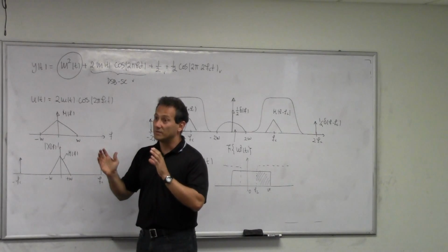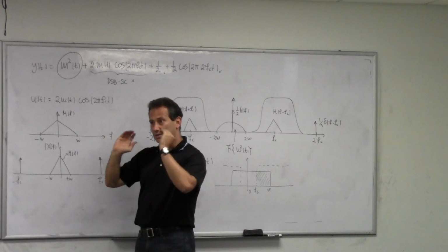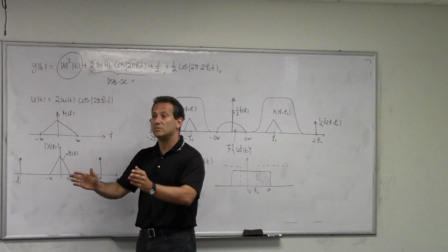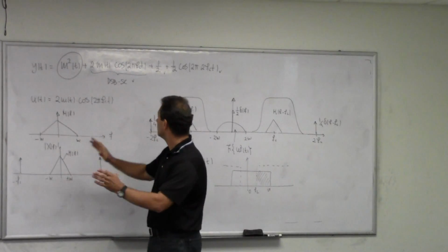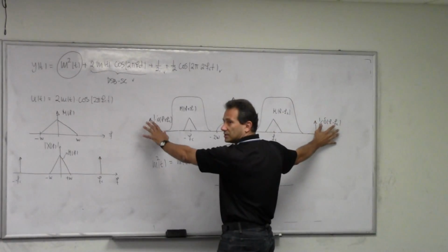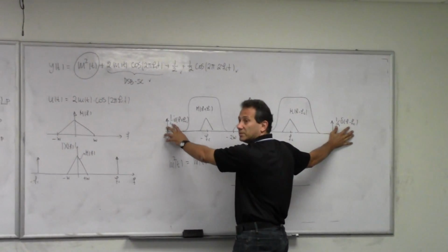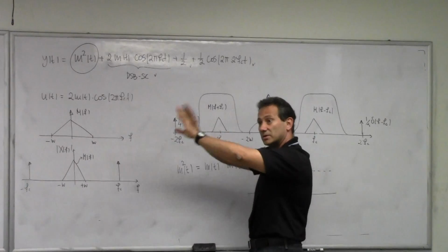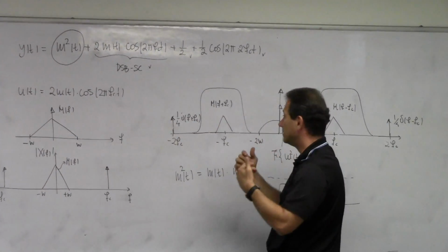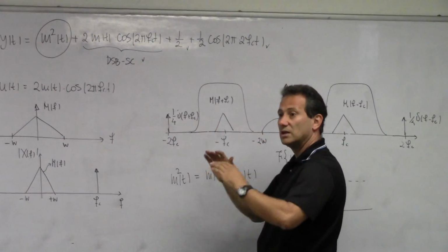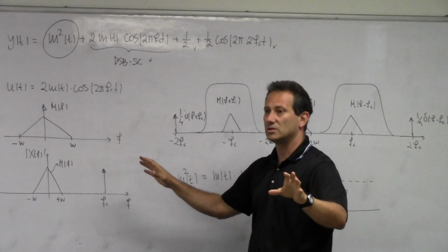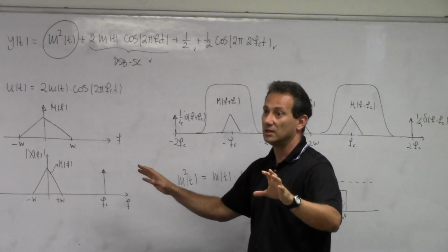Now, the specific use of the band pass is on the transmission side as an out-of-band emission rejection filter that gets rid of all of these extraneous components that you should not be transmitting. So that's when you transmit. And on the reception side, the purpose of the band pass is to reject the noise that is outside of the band of your signal.